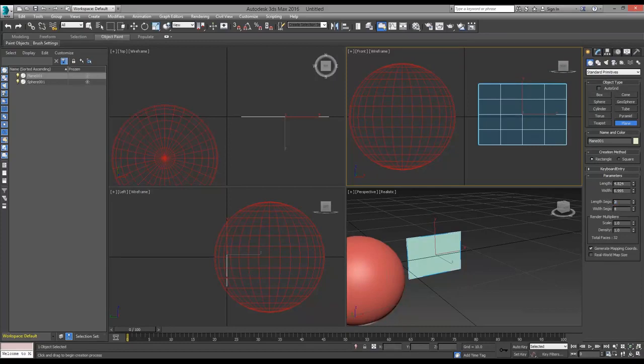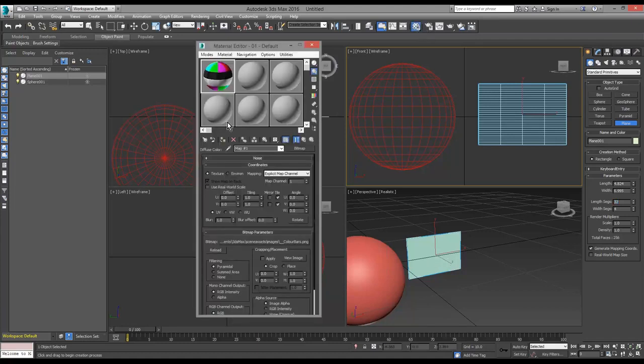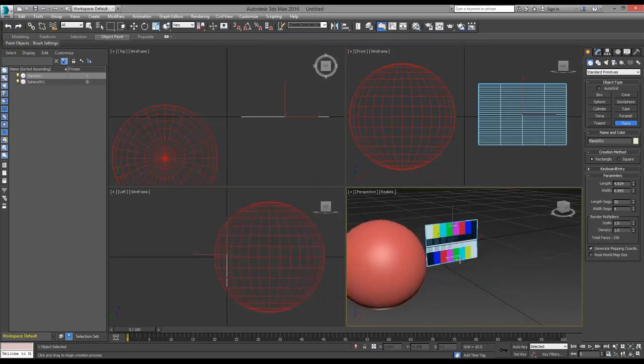Of course, it doesn't really make a lot of sense. But if I set it up to 32, the shaded result, if I put a material on it, is not changing because it's just a planar surface. So having a lot of segments in here doesn't really give you any advantage. It's just eating up your performance.